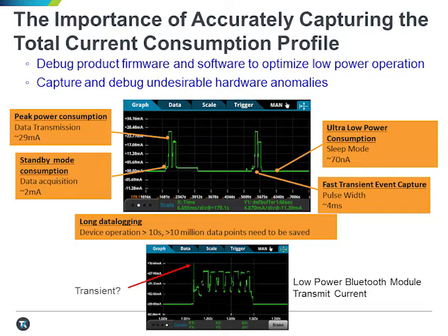With an in-depth understanding of your load current, you can see how much current each operating state is consuming. That can help uncover problems or suggest ways to revise your control code to possibly keep some components in lower power states or de-energized for longer periods of time.